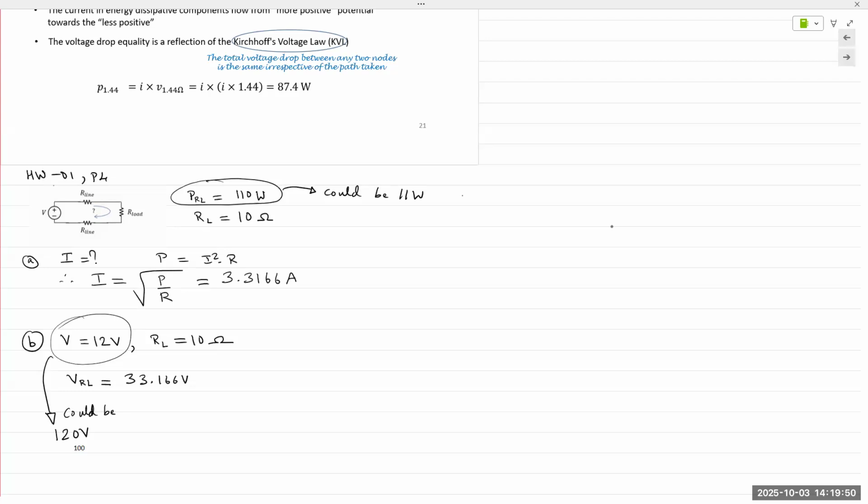So the question being asked is, wouldn't we have to account for the resistances? The answer is yes and no, because actually, as far as this question goes, no, because this question states the power that is provided is dissipated only in the load resistor, not for the entire system. It only refers to that load resistor, nothing else.